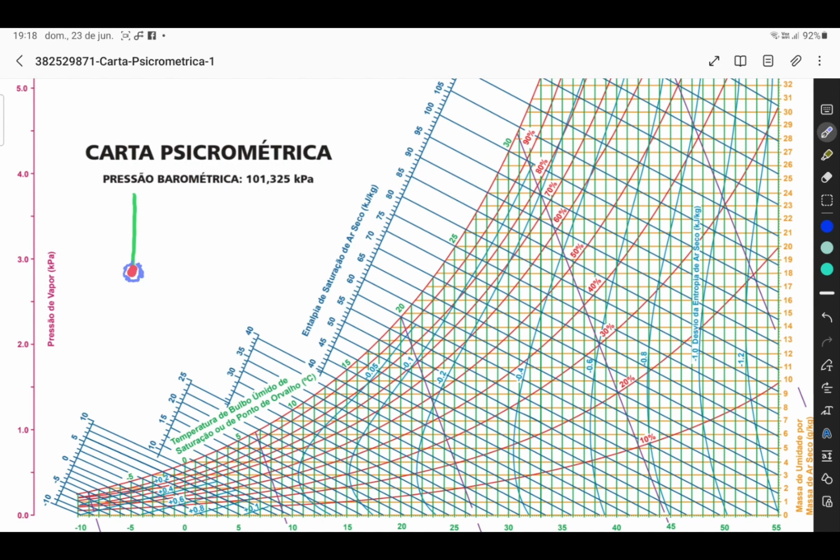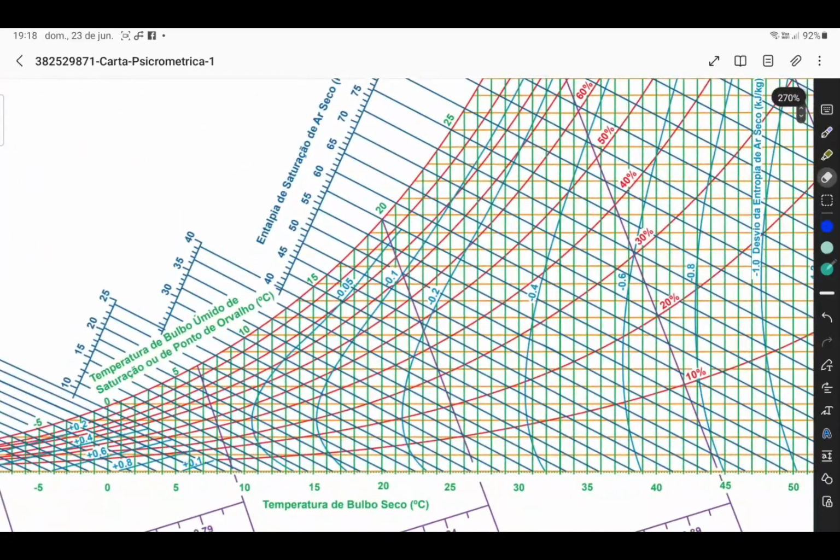We sometimes say that the dry bulb temperature is the temperature that we measure, and the wet bulb temperature is the temperature that we feel. When we sweat, exercise, and sweat to balance our body temperature, our body feels the temperature of our sweat evaporating, which would be the wet bulb temperature. The wet bulb temperature is indicative of the amount of moisture present in the air. For example, the wet bulb temperature is almost always lower than the dry bulb temperature.